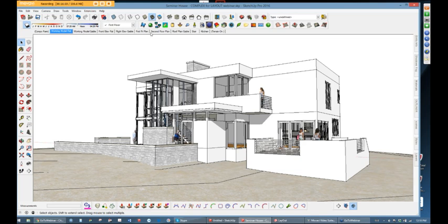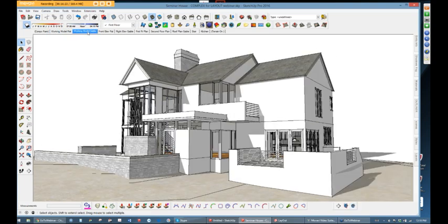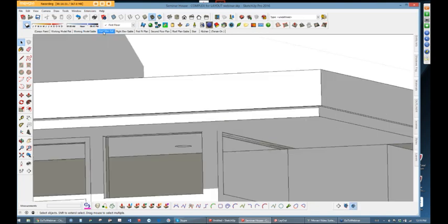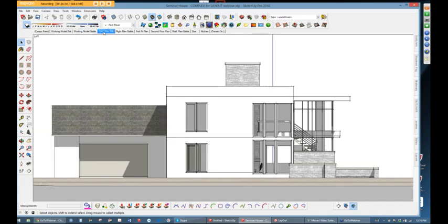You'll notice that these are all made up of scenes like we talked about last time. And these scenes are basically recalled in layout. We'll get actually to that before we're done today. So this was one where I had the client, they wanted to look at roof pitch, a pitched roof and a flat roof. So these are different scenes, exhibiting that. Elevations, and we'll show you how to do this. This is the kind of thing, again, you could set this off to AutoCAD or Layout, whichever you'd like. It's the exact same process either way.